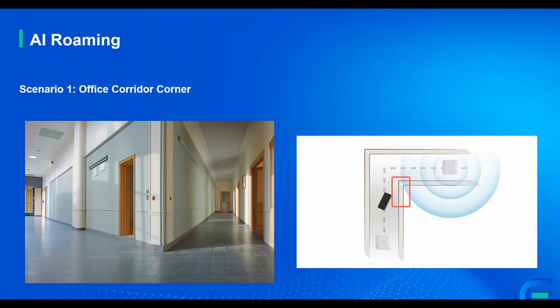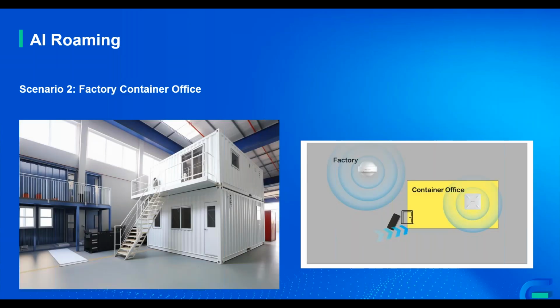As a result, the period with RSSI drops on this new station will be shortened. Maybe we cannot remove it from the equation, right? But it will be shortened. So the overall roaming experience will be improved for the user.